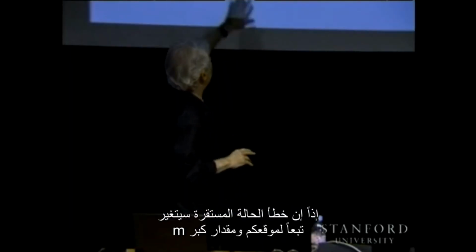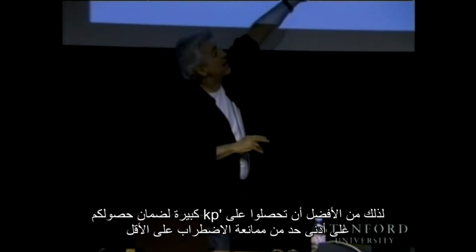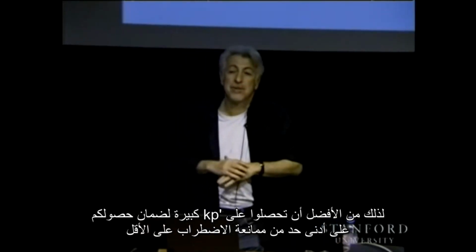And if m is changing, your stiffness is varying. So you do not have constant stiffness over the workspace as you vary m. So your steady state error will vary depending on where you are and how big your m is. And you better get a large Kp prime, to guarantee that you have a minimum disturbance rejection.